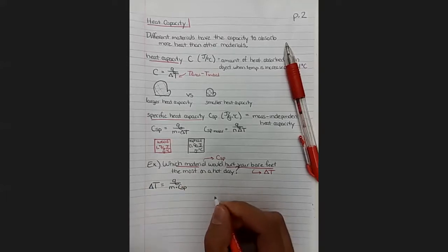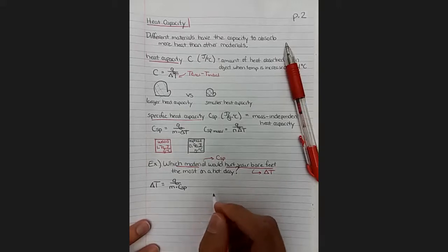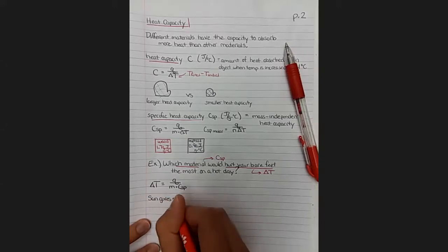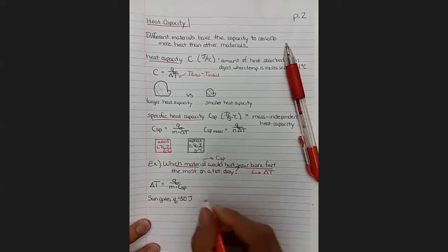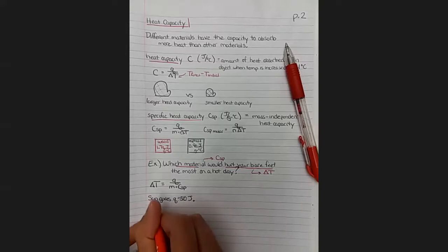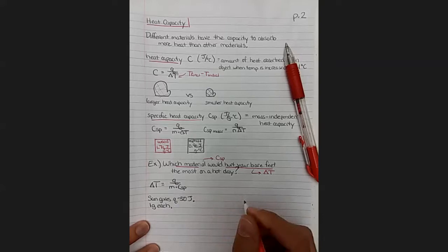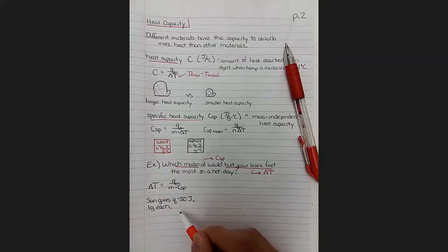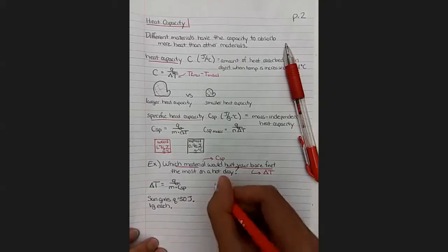So I'm going to do a theoretical calculation for the two materials. So I need to make up some variables for my condition. So let's say they're sitting outside in the sun, because that's what you do when you build a deck. And let's say that they've been sitting out long enough that the sun has given them 50 joules of energy. And let's simplify by saying we have 1 gram of each material. So the amount of heat is the same, the size of the material is the same. Let's see how much the temperature changes.